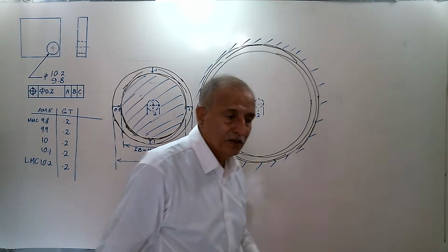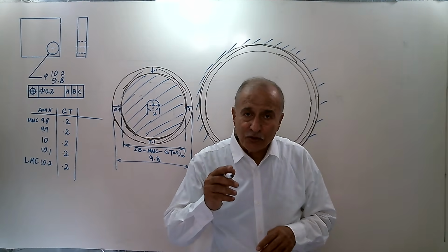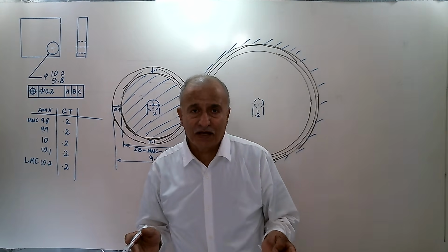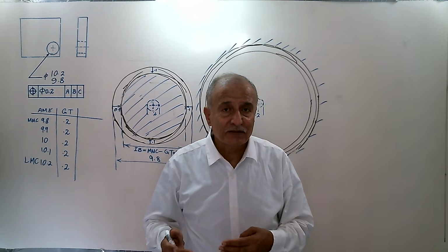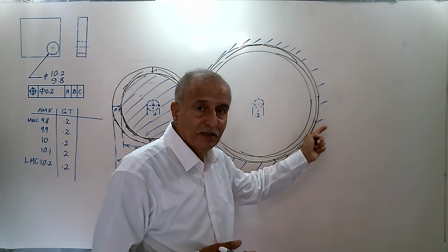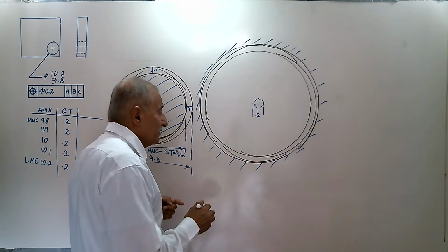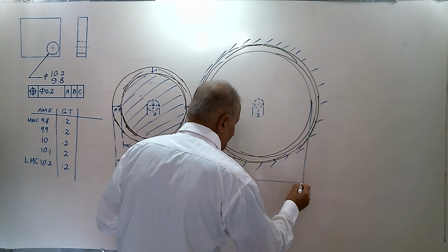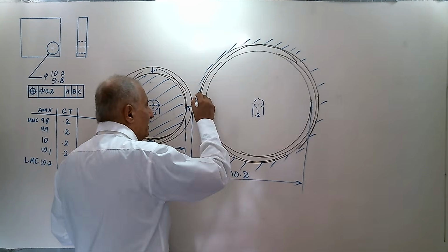If for any reason you consider that you produce at 10.2, but you have 0.2 error in position of the axis, or 0.2 error in the straightness of the axis, any geometric tolerance that can apply to a feature of size, then we have a border here that the designer tells the manufacturer: don't go outside of this border. This is if the ideal case was 10.2,